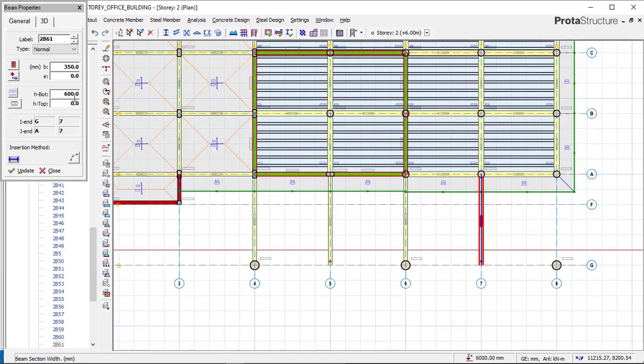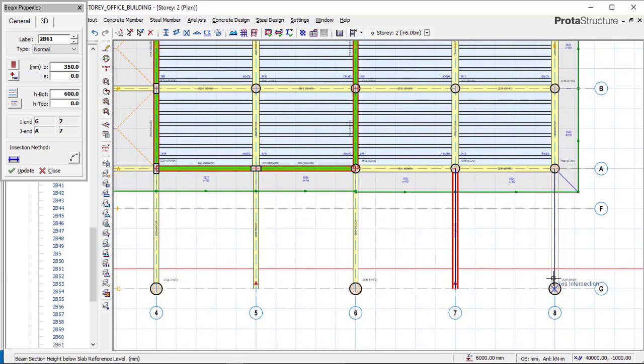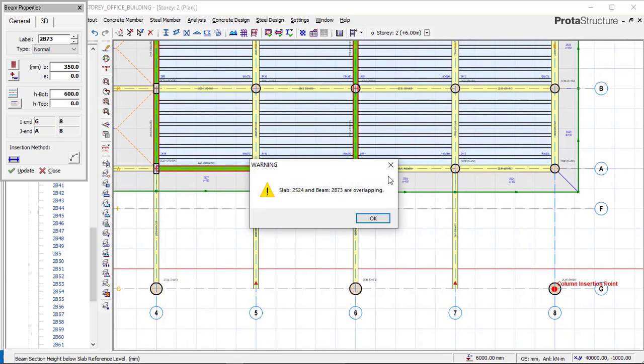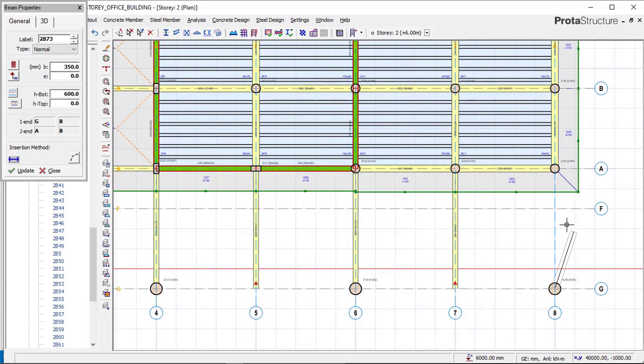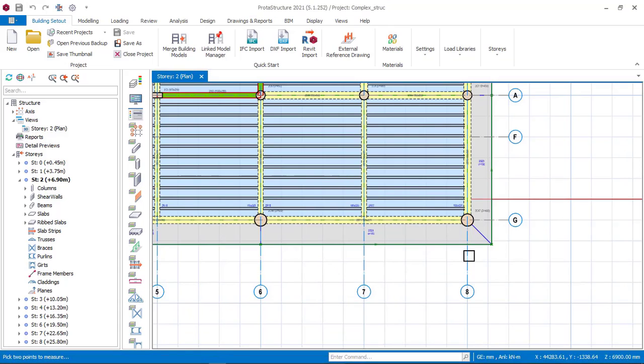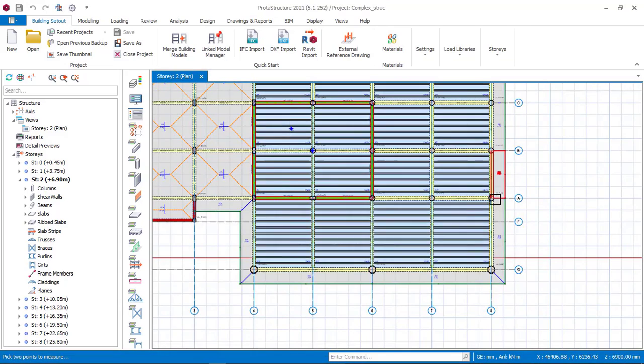So just do that right now. Input 350 and set it as our depth, and then input this just here. Okay, sorry. Let us check what we have just here. Let us confirm what we have there. Okay, we don't have a slab at that point, cantilever slab. We don't have it there.